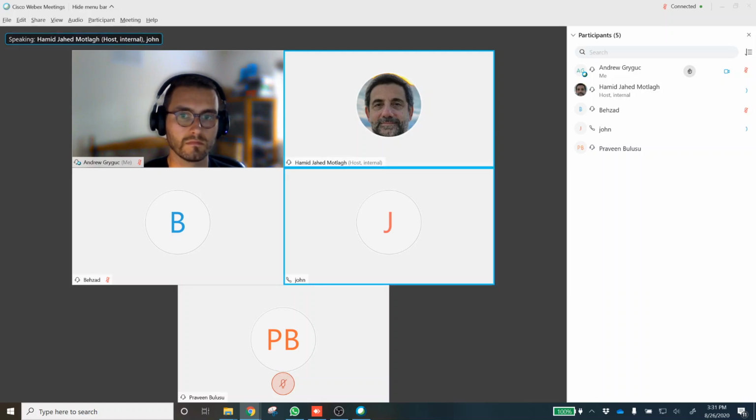The as received material, the bolt, when it comes to you, it will be already case hardened. So when you machine it out, that will be removed, because it will be only a few microns right on the surface when you machine the sample. So I can give you a specification of the hardness, and it is a few microns on the surface. I can give you the spec on that. I think that spec is important to know, first of all, for machining purposes, and then secondly, for knowing what would be the type of hardness we are dealing with after case hardening for the test.